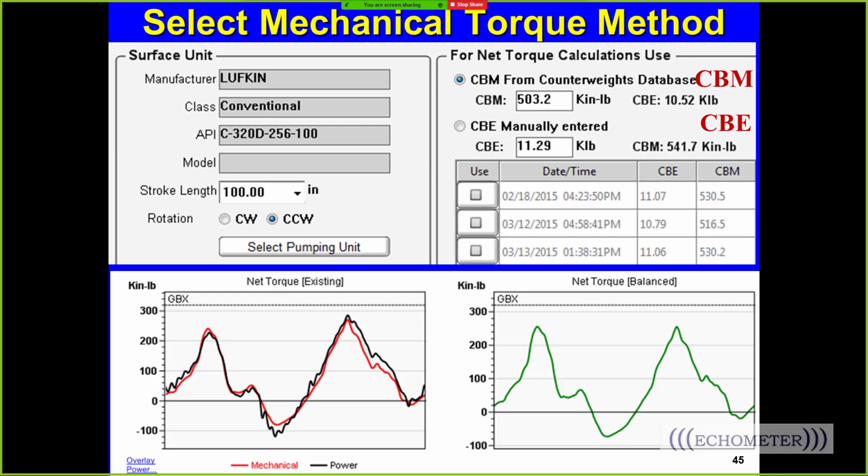When Norm Hind did a presentation sometime in the past at the short course, there's a paper he wrote about gearbox ratings for certain speeds, and most gearboxes are rated for like 25 strokes a minute without any harm. So there's not really any speed limitations on the gearbox.